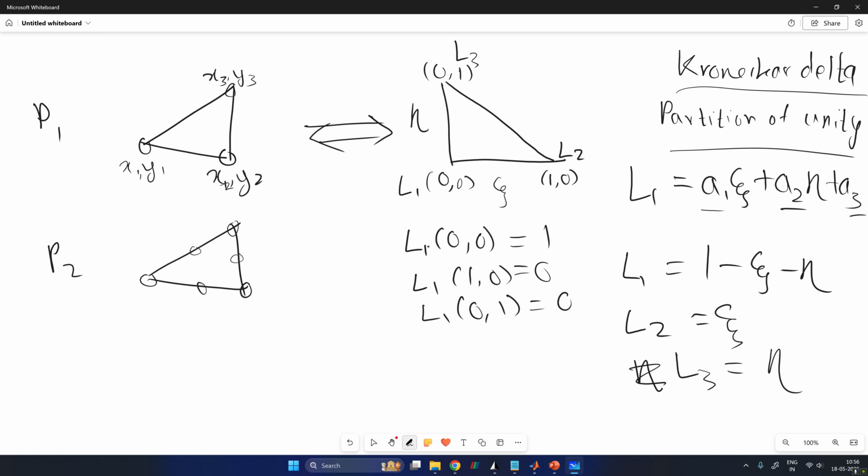Complicated and very different kinds of elements are available in finite element theory, but we are just interested in multiphysics and CFD kinds of applications, and for them these kinds of shapes are commonly used. For P3 you would have two nodes on each edge, and one node in the middle. So this is your cubic triangle.